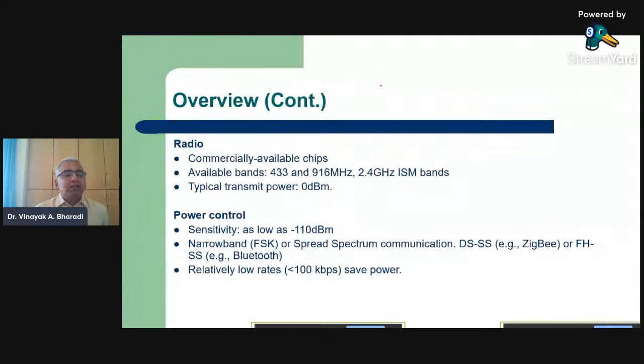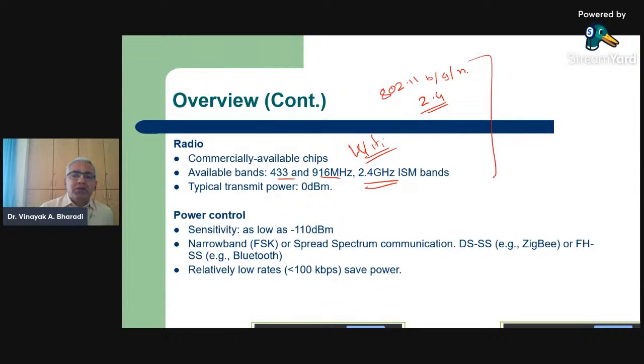For communication standards, we have discussed that wireless bands are there. Our NodeMCU had 802.11 b/g/n compatibility, and it was using the 2.4 gigahertz ISM band. There are other bands also available for this Wi-Fi communication. And there is no other option, because the best alternative for large-scale deployment is wireless communication only. So we have to have a system which has this wireless communication interface.